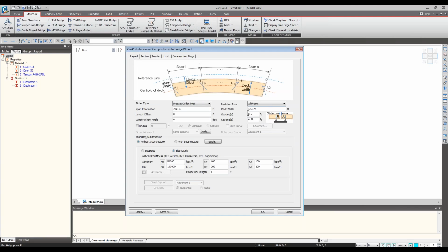And when I come back to the layout, I actually forgot to mention this portion, but you can specify the spacing between the girder ends and the support ends. And how this will help is it's actually the distance that the girder will be disconnected during the stages before the deck is composite. So after the concrete is poured, it's actually going to be poured gapping, filling this gap between the girder to girder.